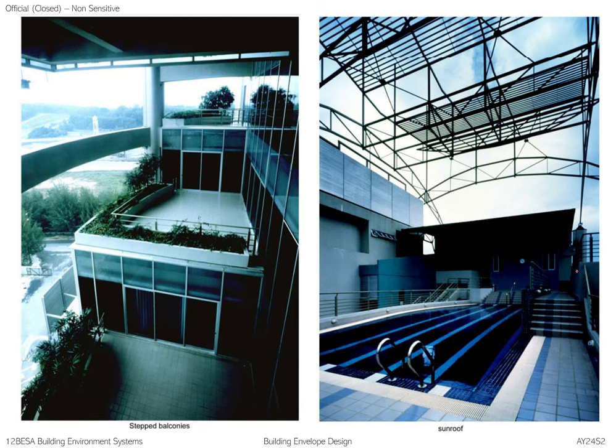Okay, there are step balconies. As seen just now, you have curtain walls here, but the curtain walls are recessed quite deeply on the inside. So you have the benefit of diffused daylight, the benefit of views to the outside, and at the same time a reduction in solar heat gain, which makes the space very comfortable.